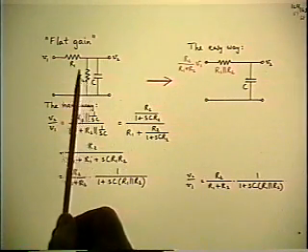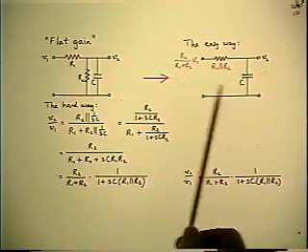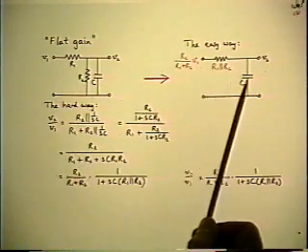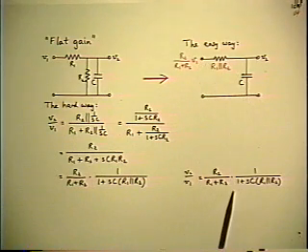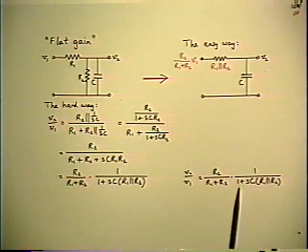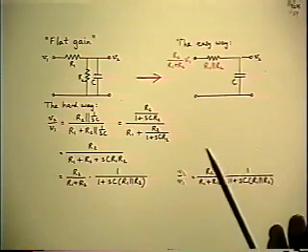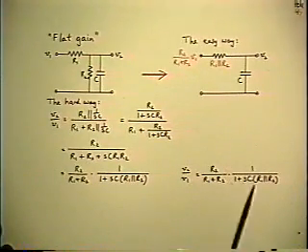Use Thevenin's theorem to absorb the R1 and R2 into an equivalent, which reduces it from a 2-loop circuit to a single-loop circuit. Write the answer as a voltage divider, and there's the answer in one line. Same answer. No algebra at all, and it's automatically in low entropy form.